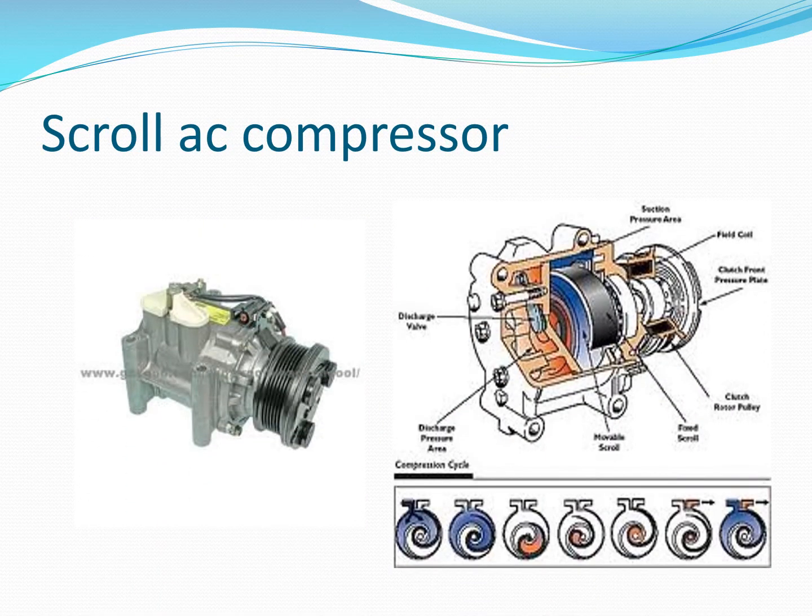Scroll compressors look pretty much the same as the vane compressors on the outside, but inside they are very different. If you look across the bottom of this diagram, you'll see that as the refrigerant is pulled into the outside of the scroll, the scroll is going to be rotating inside another scroll and is going to push that refrigerant towards the center.